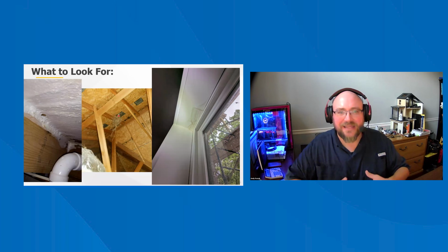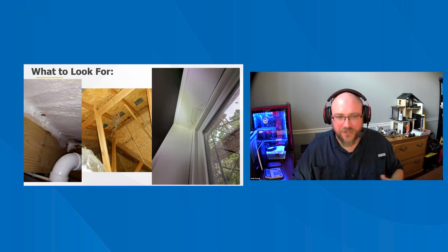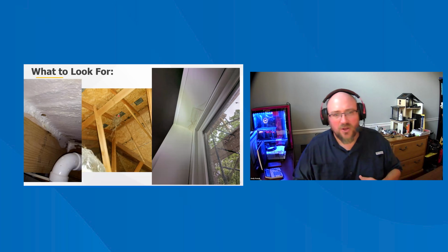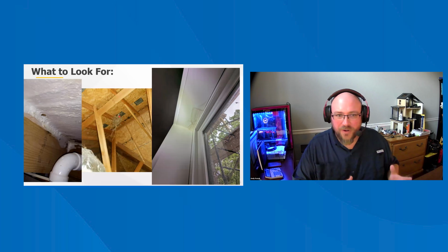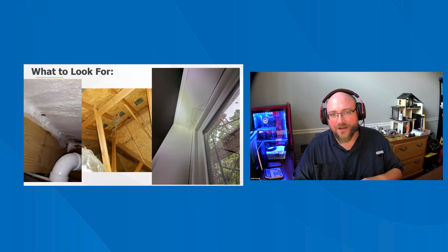They're all expelling warm air out of them, from the bathroom or from the kitchen or hot air from the attic. Well, birds really love that warm air. And so if the vent has been damaged or the screening has been damaged on any of those, or if it was never installed, that's where those birds like to nest and eventually will block that up.